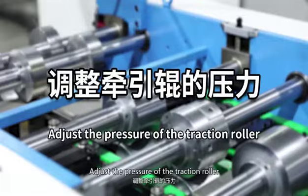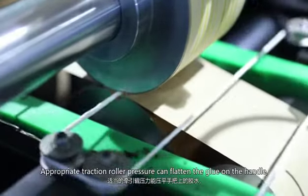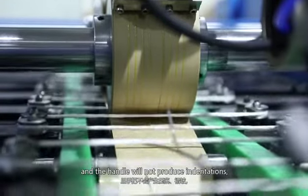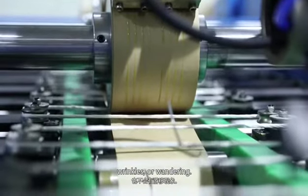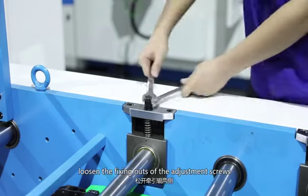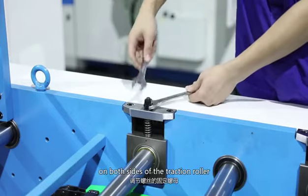Adjust the pressure of the traction roller. Appropriate traction roller pressure can flatten the groove on the handle, and the handle will not produce indentations, wrinkles, or wandering. If adjustment is required, loosen the fixing nuts of the adjustment screws on both sides of the traction roller.